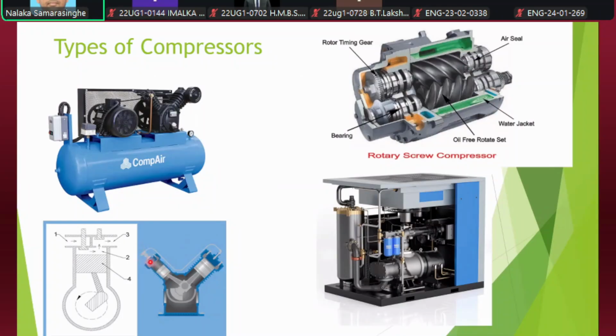When the air is supplied from the first cylinder to the second cylinder, if you have cooling fins along this path, that heat can be dissipated and you can cool the compressed air. That's what we usually call intercooling. Intercooling means cooling air between those two stages of compression.